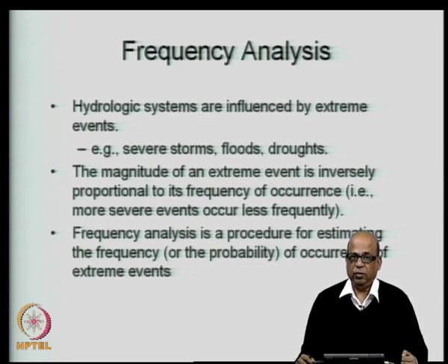Now, the frequency analysis is a procedure of estimating the frequency or the probability of occurrence of extreme events. That is, we may be interested in answering the question, in how many years a flood of a given magnitude is likely to occur on an average, or what is the probability that in a given year a flood of a given magnitude will occur. These are the types of questions that we would be interested in answering through frequency analysis.